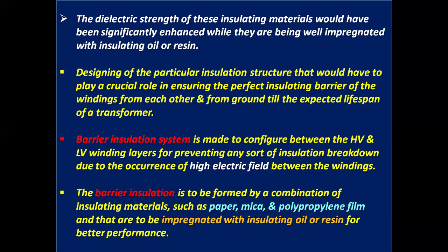The dielectric strength of these insulating materials is significantly enhanced when they are well impregnated with insulating oil or resin. Designing of the particular insulation structure plays a crucial role in ensuring perfect insulating barriers of the windings from each other and from ground until the expected lifespan of a transformer.